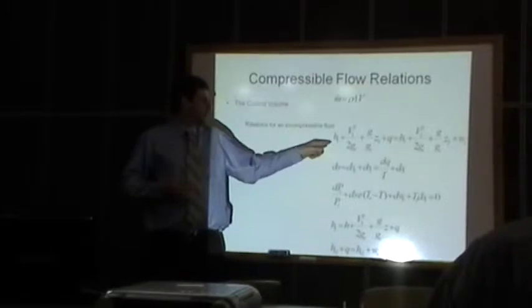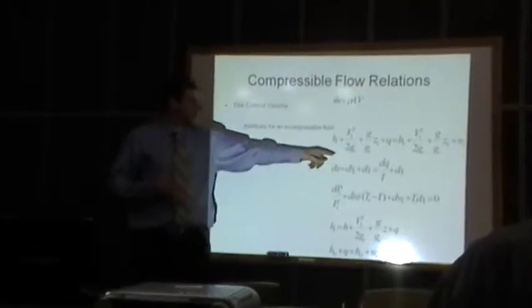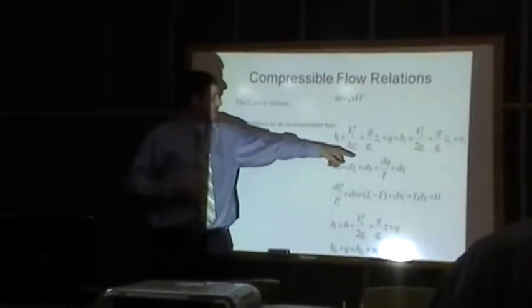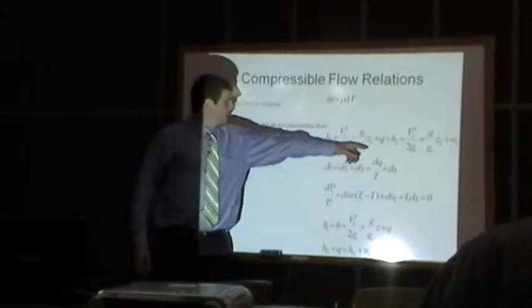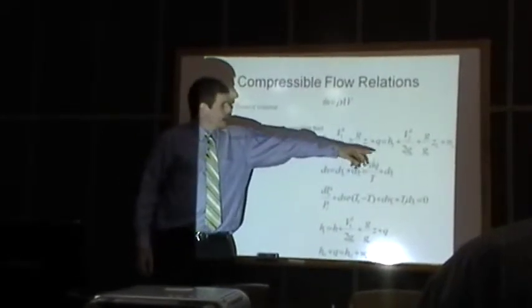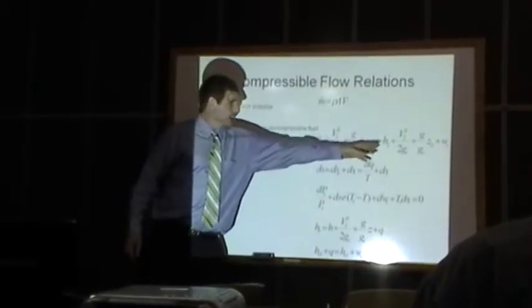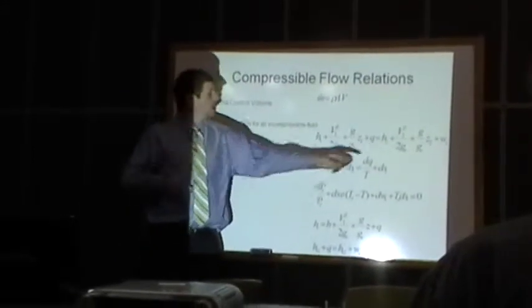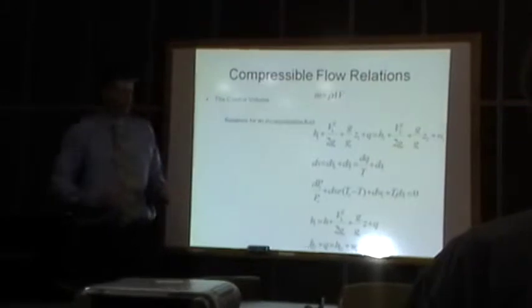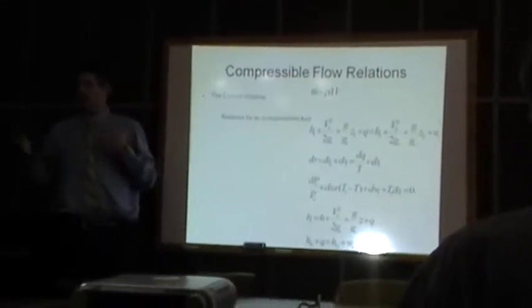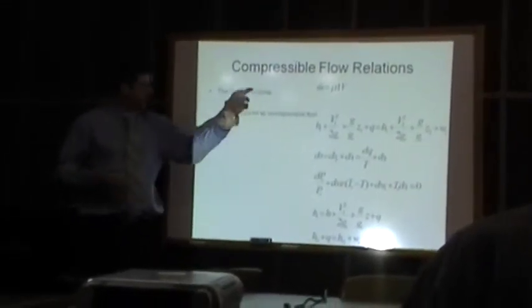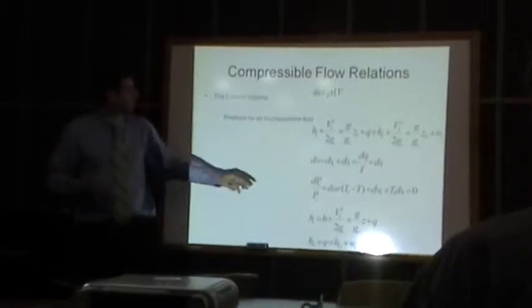The second is conservation of energy with enthalpy, kinetic energy, gravitational potential energy, and heat, and essentially the same on the other side for a different point, and shaft work. There's no work in any of these tubes, therefore we can neglect that term, which I'll talk about later.